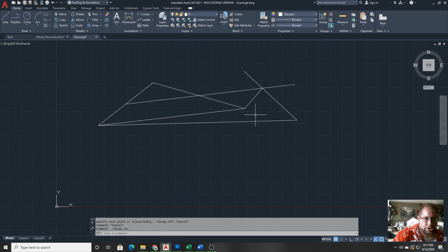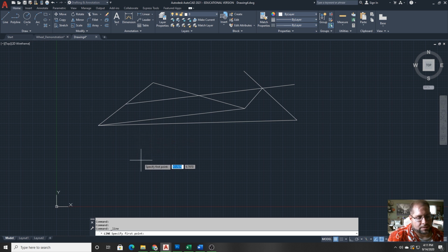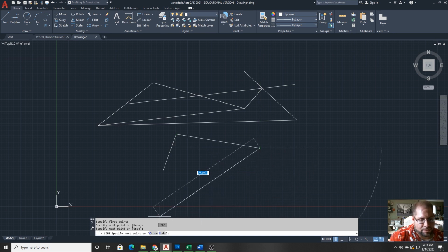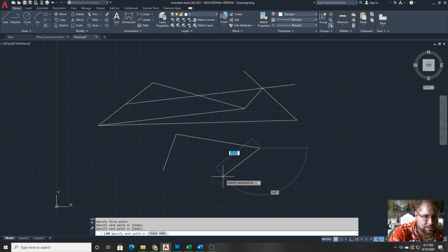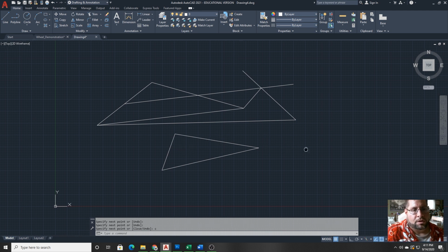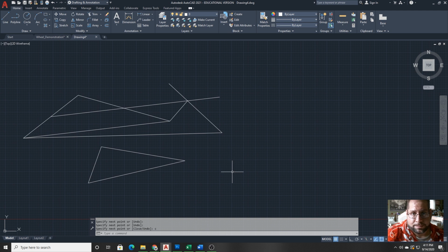The last thing I wanted to show, as far as drawing the lines are concerned, regarding the hotkeys that are on the bottom, is that closure piece. So let me just draw two lines again. Again, the options don't pop up right away. So I'll draw my two lines, and then wherever I am, I can go ahead and press the C button or click this. I'm going to press the C button, and as you can see, it starts typing it by the cursor, and I'll press enter, and it will close that particular series of segments, remembering where my start point was. Okay, so that's object snap and drawing lines.